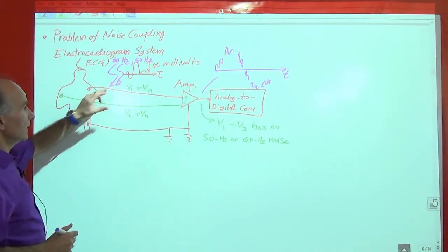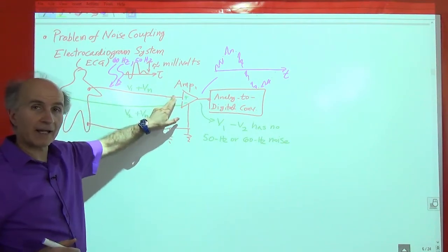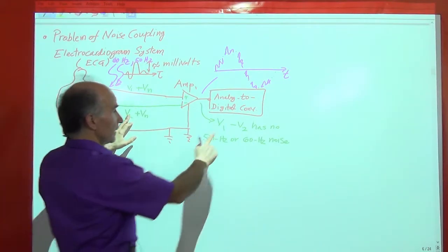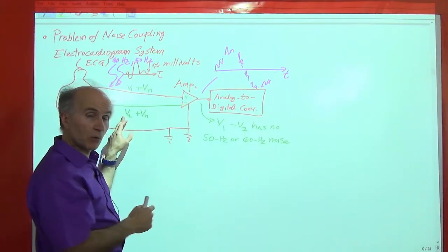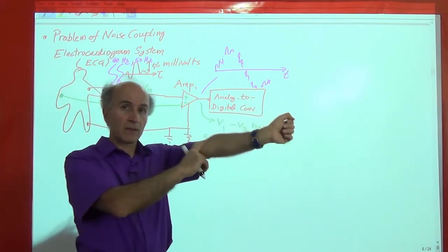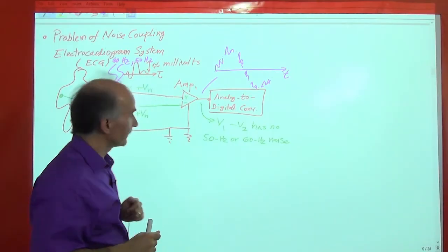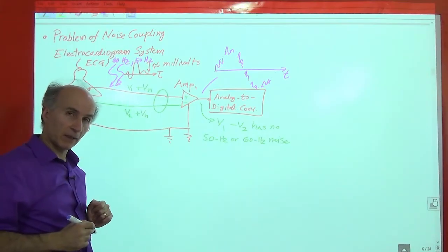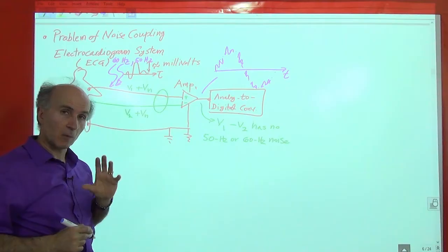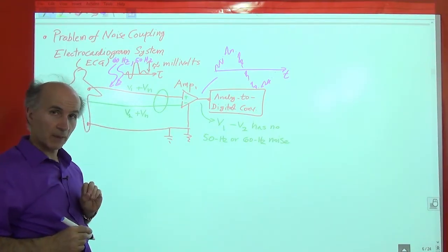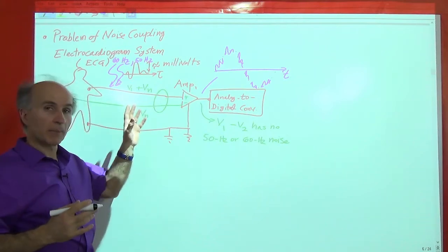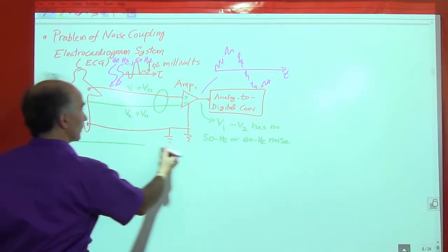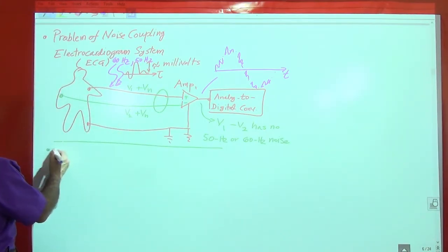Okay, so what we did here is we went from one line carrying the desired signal to two lines carrying the desired signal. Of course, our hope is that V1 minus V2 is not zero, meaning that V1 and V2 don't look the same. And they don't, because one is attached to this arm, one is attached to this arm. All right, so these two lines together carry the desired signal now. And that forms the basis of what we call differential signals. So I have to formally introduce differential signals, but we can see from here what will happen. Okay, so let's go and talk about differential signals.